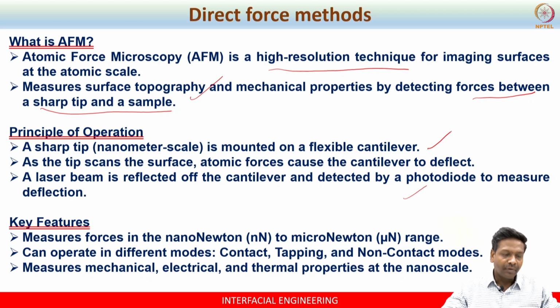Okay, some of the key features of this technique is you can measure forces in the range between nanonewton to micronewton. Okay, like your SFA, right? What we have seen in a similar range can also be obtained using the AFM. So this technique can be operated in three different modes: contact mode, tapping mode, and non-contact mode.